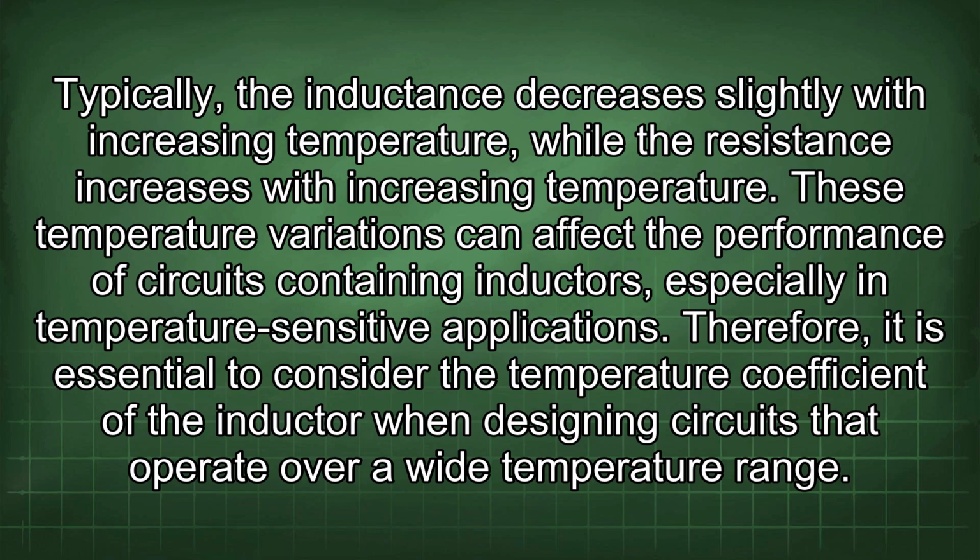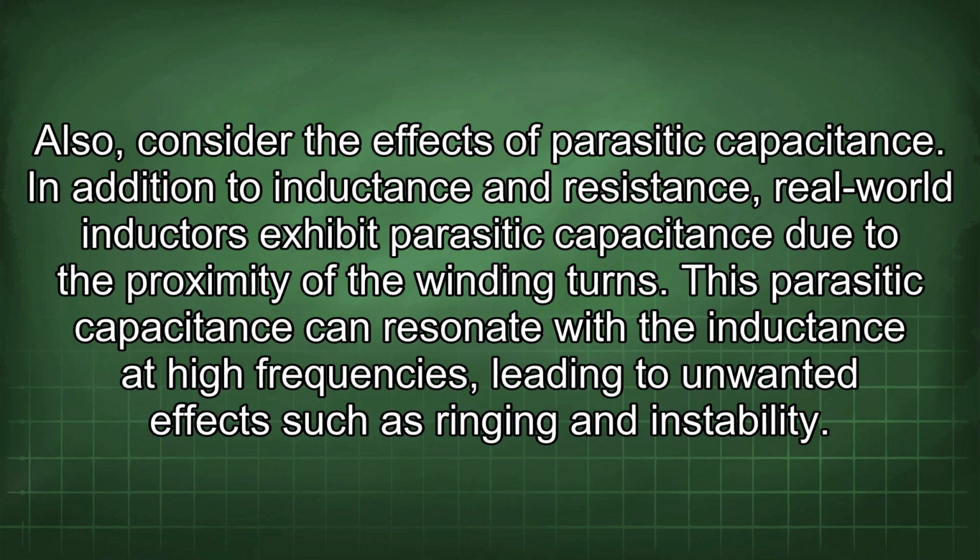Typically, the inductance decreases slightly with increasing temperature, while the resistance increases with increasing temperature. These temperature variations can affect the performance of circuits containing inductors, especially in temperature-sensitive applications. Therefore, it is essential to consider the temperature coefficient of the inductor when designing circuits that operate over a wide temperature range. Also, consider the effects of parasitic capacitance.